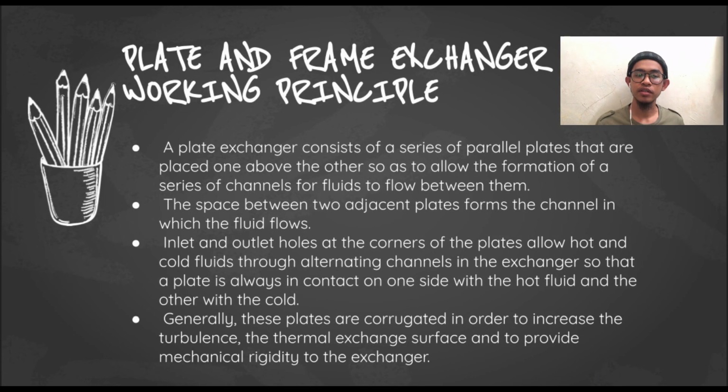Plate and frame exchanger working principle. First, a plate exchanger consists of a series of parallel plates that are placed one above the other so as to allow formation of a series of channels for fluid to flow between them. The space between two adjacent plates forms the channel in which the fluid flows.